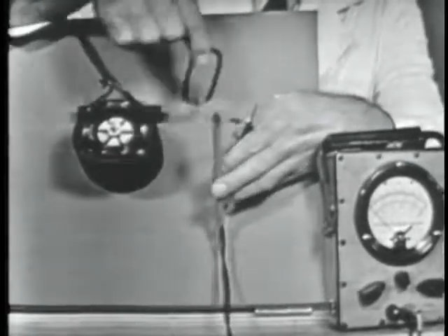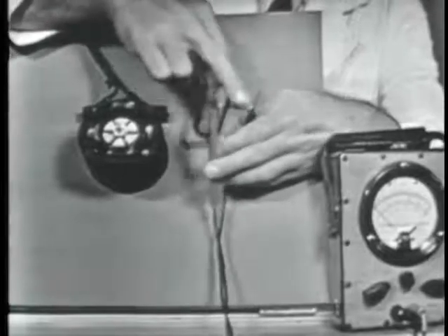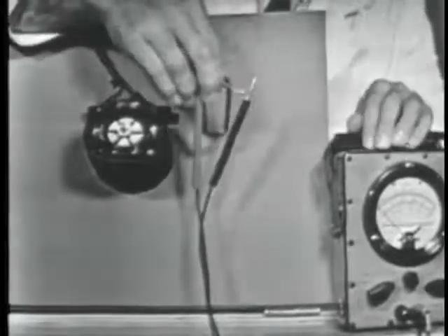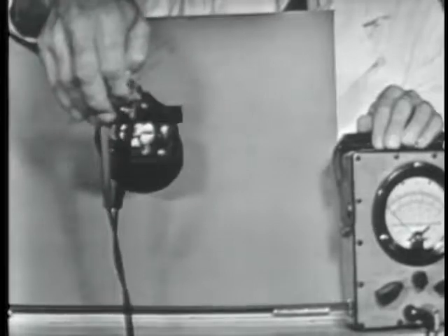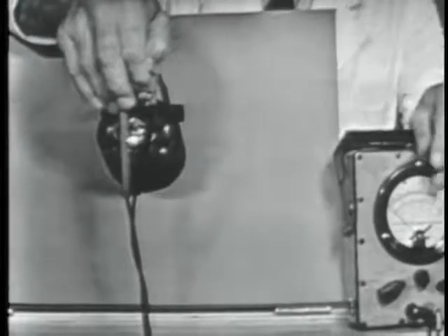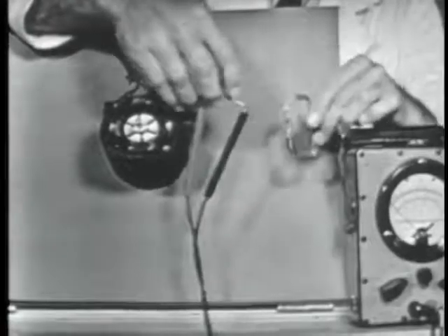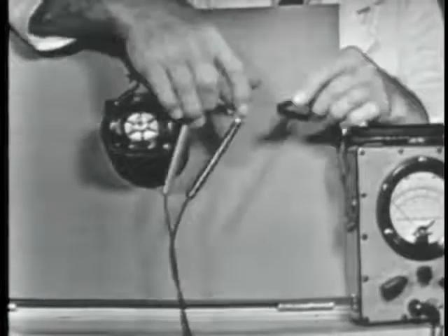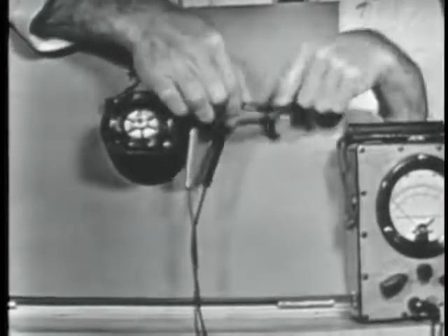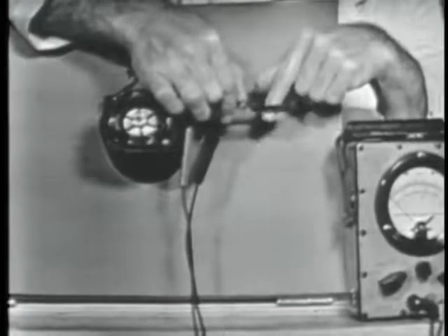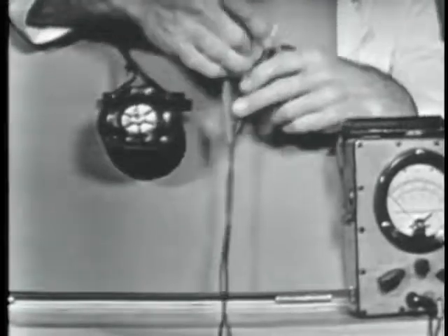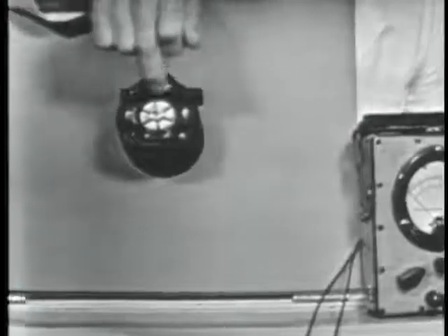Okay, and we proved that with this little loop of wire, the resistor and the PSM6. We put the loop in the field windings, and the PSM6 showed us that we did have a voltage induced into the loop, causing current to flow. Once we had current flow, we know that the loop had to become magnetized and exhibit a north and a south pole. And once we get it magnetized, it has got to follow the rotating magnetic field.